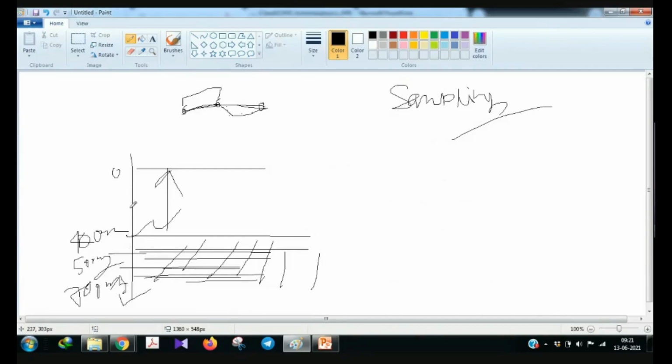Now if you fix the time duration less, let's say 350 nanoseconds, then you are losing this much data, and once you come back from the field, it will be very difficult to go again and do the survey. So during the survey, you have to keep the time duration in mind.